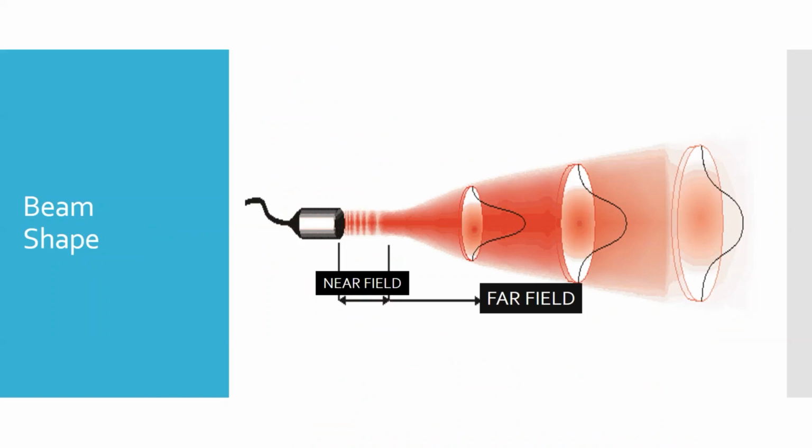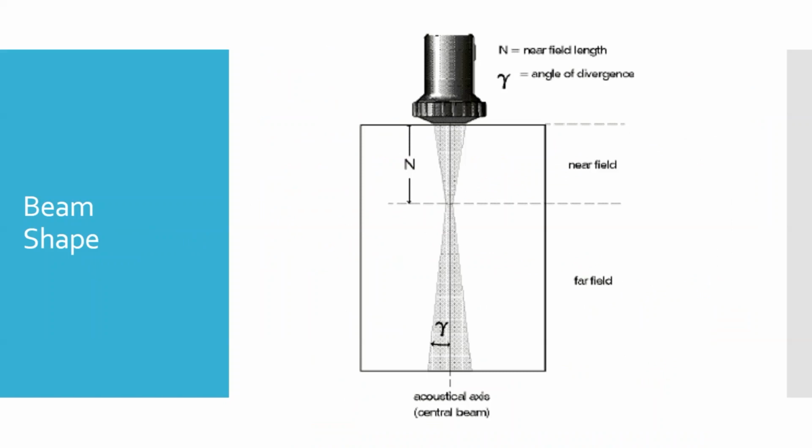But if we had a perfect material that had no impedance, no acoustic attenuation, if you didn't have any loss of energy from the mechanical properties, you would have the same amount of energy at any point. It's just spread over a bigger area. So the energy per given area does decrease as you move further away from the probe. And then to couple that, we don't have any perfectly acoustic conductive materials, so there's a certain amount of attenuation taking place as well, just from the acoustic impedance that happens.